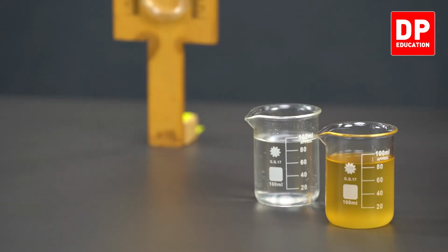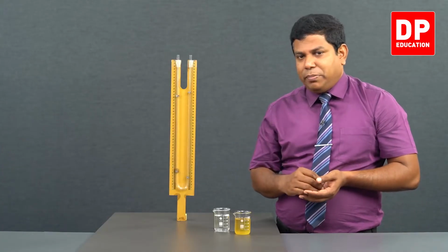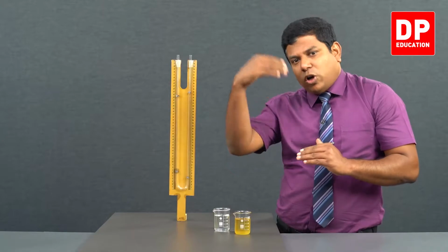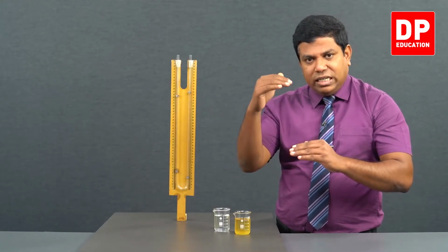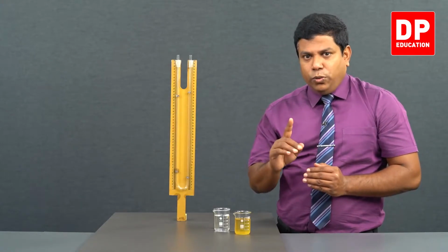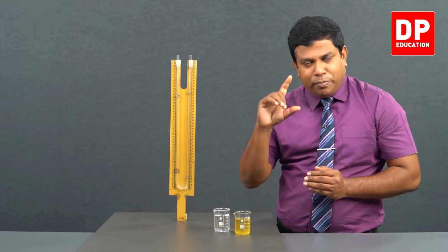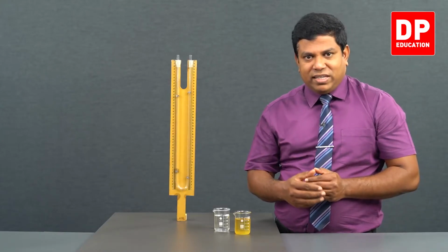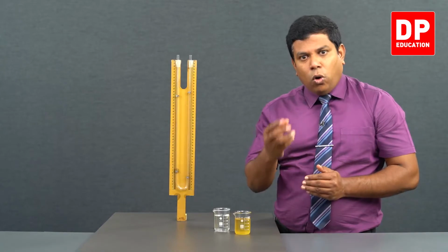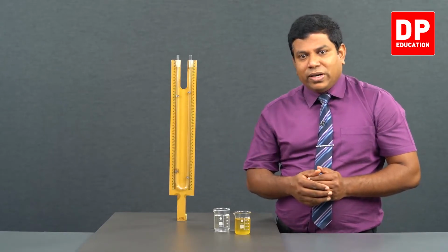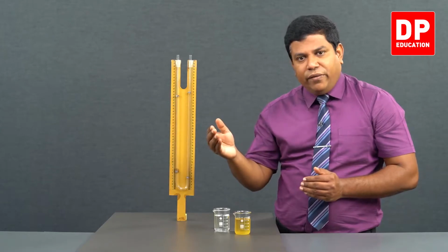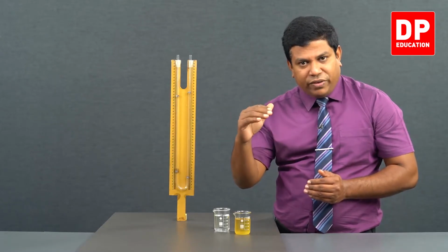So, at the water-oil interface, if you check the pressure, that pressure has to be equal to, above that interface what do we have? We have the column of oil, and on top of that it is atmosphere. So, at the water-oil interface, pressure is going to be equal to atmospheric pressure plus the pressure exerted by the column of oil, which will be H rho G. If I say H_O for oil's height, rho_O for oil's density and G for gravitational acceleration, so, A atmospheric pressure, A plus H_O rho_O G will be the pressure at the interface, which interface? Water-oil interface.